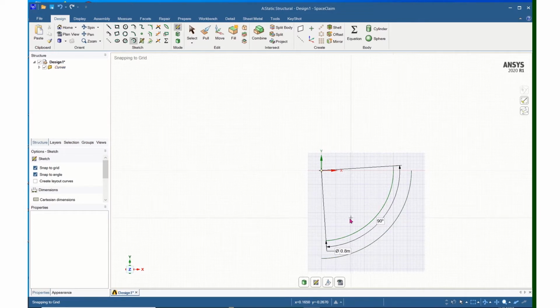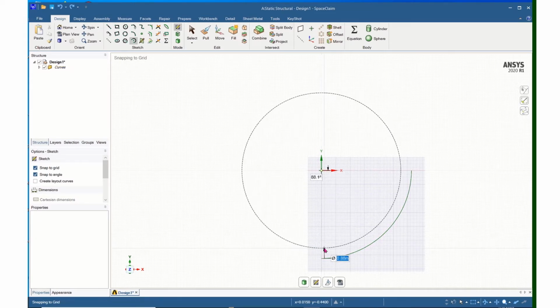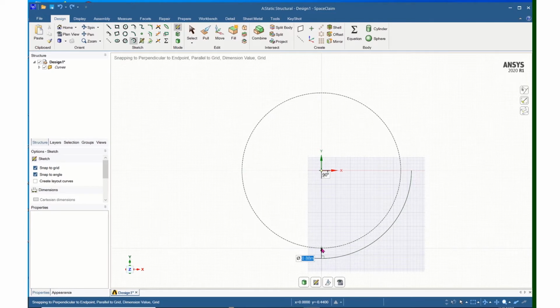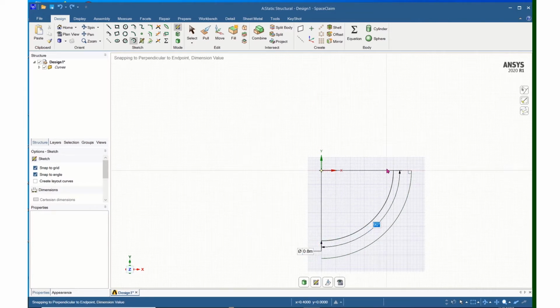You can see that I messed up here and I didn't quite get the 0 to begin with, so I will do an undo and come back and click the center point, scroll down to staying on the center line, scroll down to the distance and enter 0.8, enter, scroll around until I hit the radius and the angle that I want and type in 90, enter.